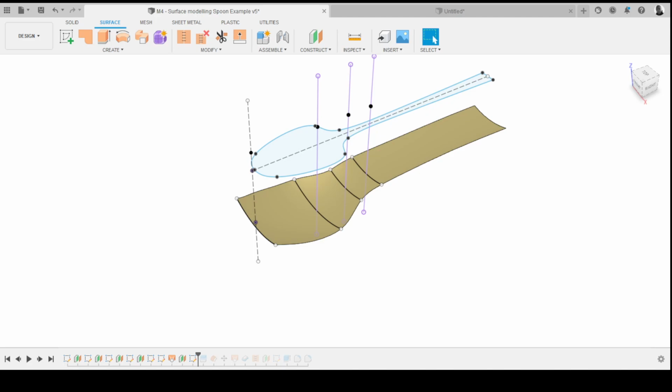Which is why, when you start modelling it, you've got to try and work out what is the best way of modelling it. For something as specific as that, what we're going to look at next week, which is the sculpt environment, is the ideal way of modelling. You get a really nice blended smooth surface. There's absolutely no reason you couldn't do what you were suggesting with lofting, a mixture of surface modelling and solid modelling. But I think sculpting is actually what you'd need to do.